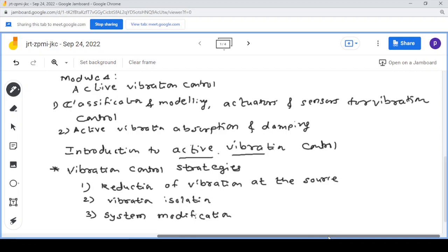The large cover panels surrounding the pump are the basic problem. To address that, we can add some ribs on the panels, thereby stiffening them so that their natural frequency is shifted well above the excitation frequency, that is above the rotational speed of the pump. This can be considered system modification, or system modification by structural redesign. So all these techniques are essentially passive vibration techniques.